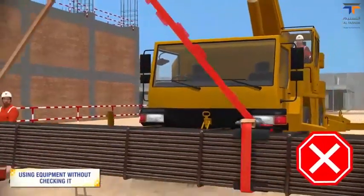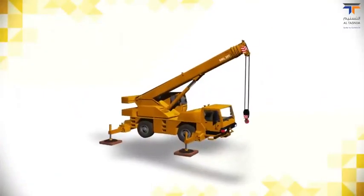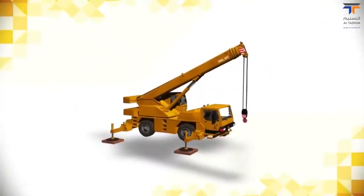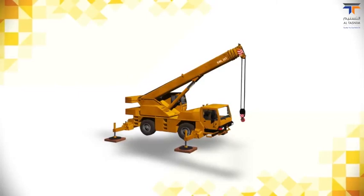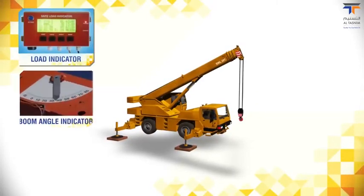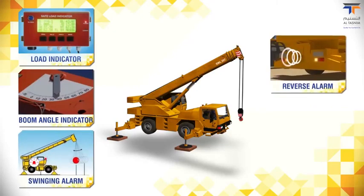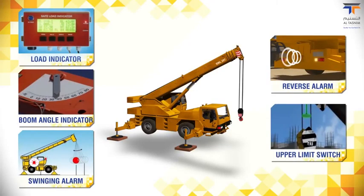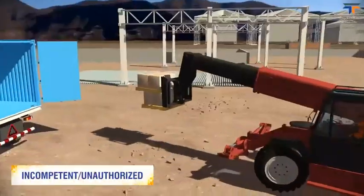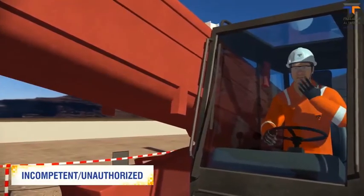Using equipment without checking it and its safety, not following the guidelines of maintaining the equipment according to the manufacturer's instructions, for example, not checking load indicator, boom angle indicator, swinging alarm, reverse alarm, upper limit switch, etc. Allowing incompetent or unauthorized staff to use the equipment.